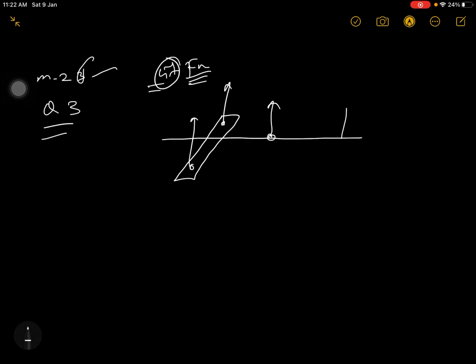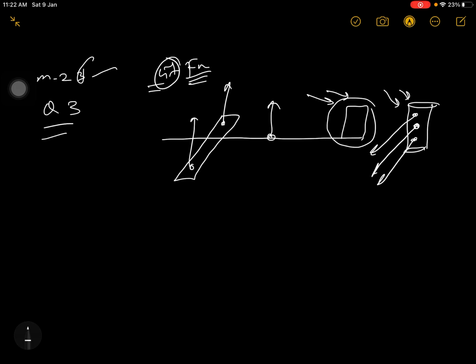In the same way, if you have a vertical tail here, then when the air hits the vertical tail, even this vertical tail is nothing but a wing, right? But it is placed vertically. So when this wing experiences some kind of air, it will generate force in this direction, correct? Because all wings generate force perpendicular to their planform area. Here we have a wing generating our lift force. In the same way, this wing, which we call the vertical tail, will produce a force perpendicular to its own surface area.